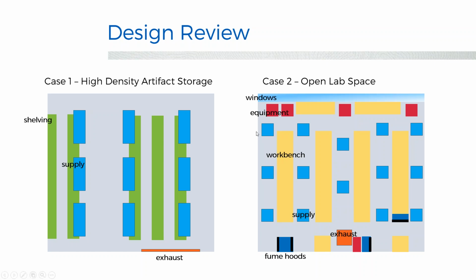So as a first pass, you can see that the equipment is releasing a lot of heat into the space. It was ovens, a few refrigerators and centrifuges, but mainly the ovens. When they were running, the heat from these would have to travel all the way through the lab, impact the occupants here, and then travel to the exhaust, which is a fairly inefficient way of capturing the heat off these pieces of equipment.